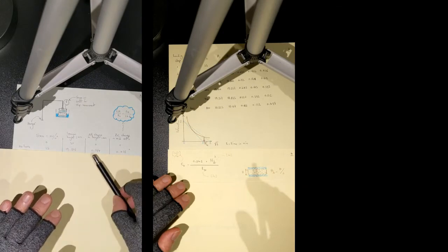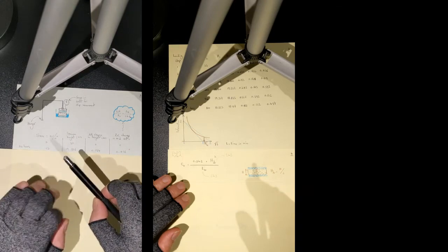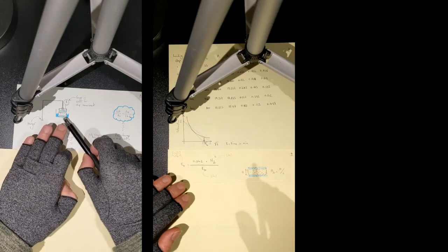Obviously 20 minus 0.194 equals 19.806. That's how we got 19.806, and that's how you measure the specimen height under 25 kPa of pressure. I remind you that at all times, your soil specimen is kept fully saturated. You can see that the water bath at all times is full of water.